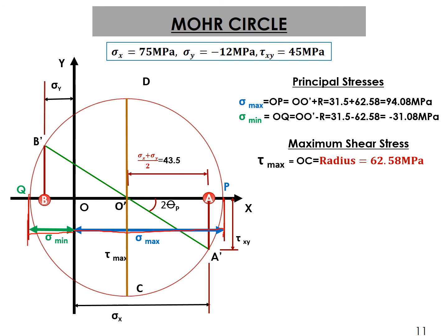Its direction we also have to find. You have to find out the angle. If you can recall, that is theta s. Now, which line gives you theta s? The plane of maximum shear stress. This green line is your xy axis. Don't forget this green line. With this green line, you have the principal axis. Now, with this green line, you have this maximum shear stress also. See in the figure, this is twice theta s.